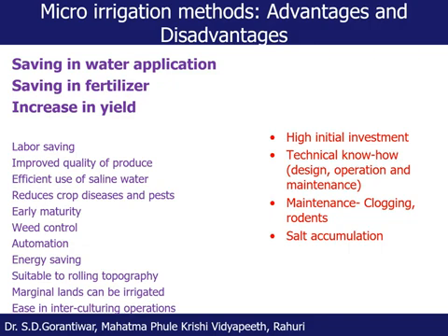But when it comes to the field, we have to distribute the water through a network of field channels, and when water is distributed this way, there are distribution losses. And when it comes to the surface irrigation layouts, that is border, check basin, or ridges and furrows, there are unavoidable application losses as well.